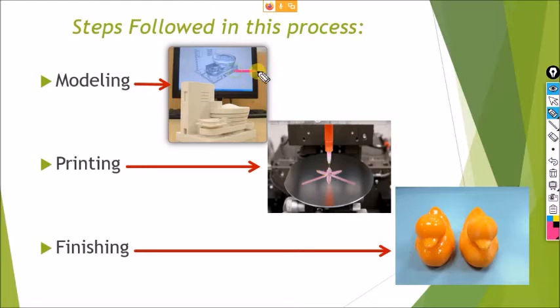But how will this particular 3D model be printed on the system, right? A machine needs to understand, so we need to communicate that in a machine language format, in other words, G codes, right? We have plenty of software available in the market where this particular 3D model in STL format will be converted into G codes. So G code is the machine language which the machine will understand in terms of x, y, z direction, how much is the height, how much is the depth, and in what way we need to do. All these things will be taken carefully.